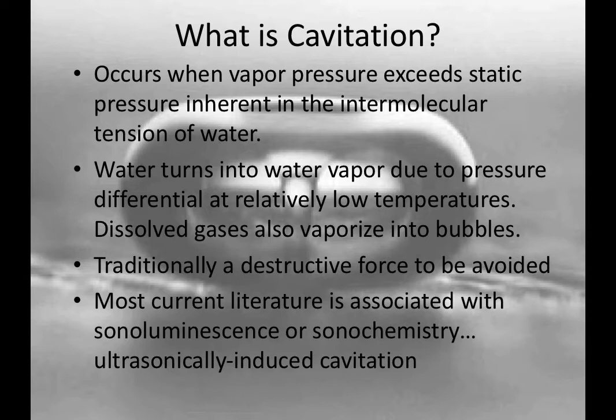Traditionally, cavitation has been considered something to be avoided by engineers. It's destructive, it chews up propellers, it chews up pumps, and that's all happening because when you have an impeller, you create a low pressure environment on the backside of your blade, and with that low pressure environment, you induce the cavitation, and we're talking bubbles on the level of a micron and smaller.